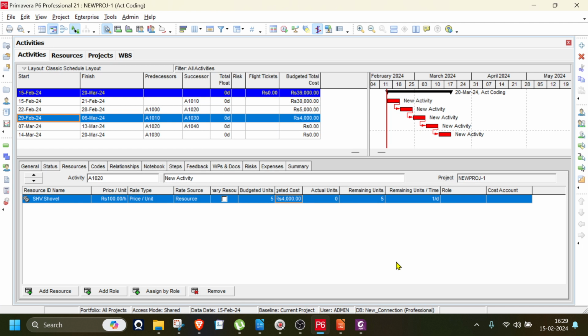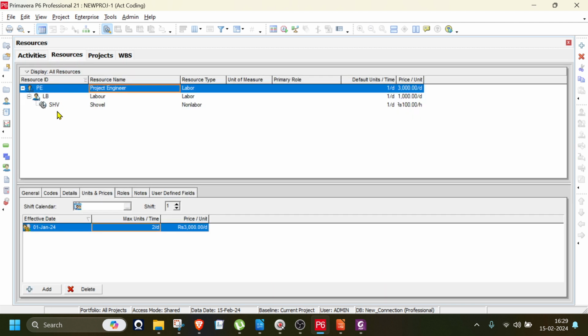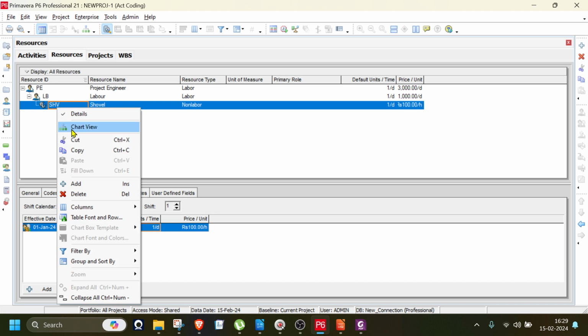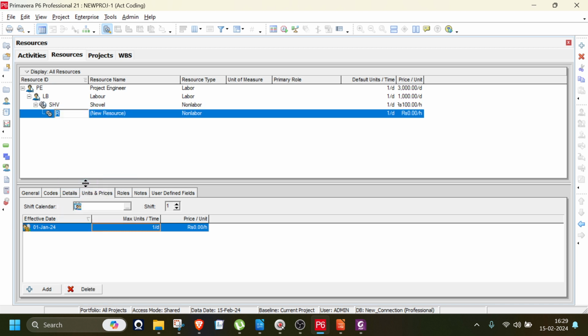Okay? Then next, the pipe is a material, right? So you have to click the material part. The unit of measures, just click the unit of measures which is meters, and assign that. Next. And here, let's say it is 600 per meter. Just put 600, it will automatically catch meter because you had already given the units.